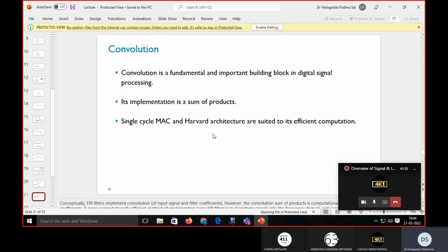One more important point is that in all DSPs, whether you take convolution, correlation, FFT, DFT or whatever equation, you have to multiply two things and sum many times. For supporting that, you have dedicated hardware, a multiplier and accumulator.